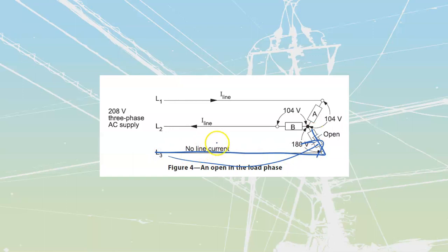So whether that line would open over here, here, or in the middle of the load, it is either way going to sever the current and it's going to do the exact same thing. What we are now going to see is a load that is going to have a voltage dropped across it. This is what's changing over here. When the load opens, I see a higher value of voltage over top of that load.